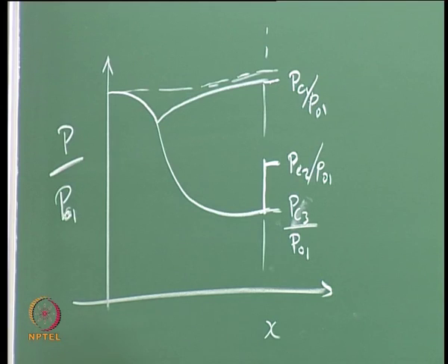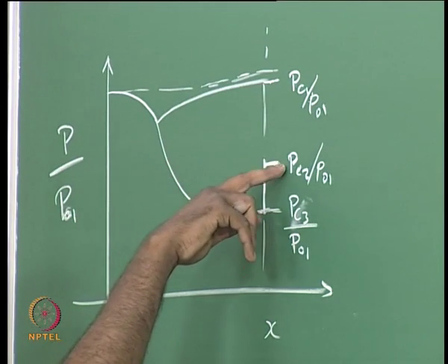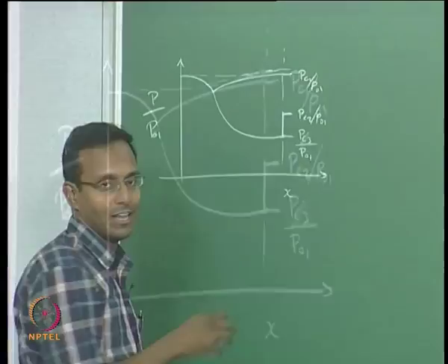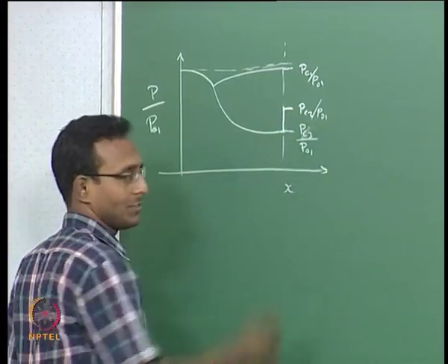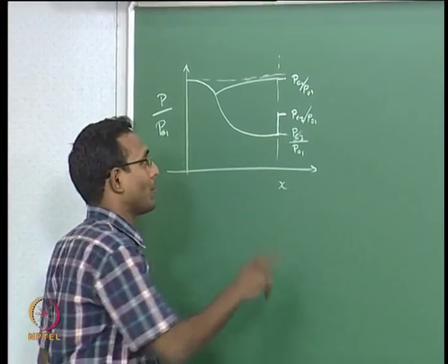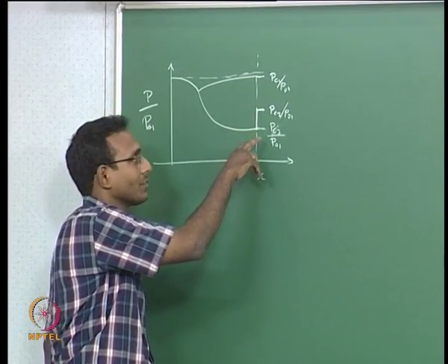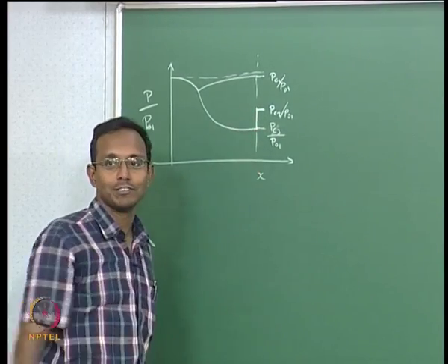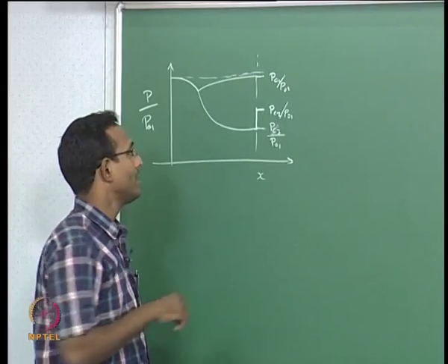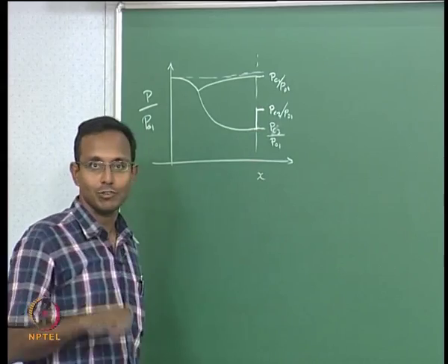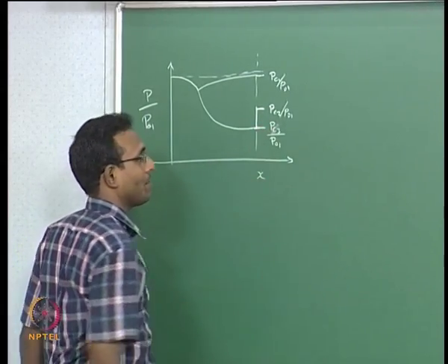Initially we said the flow changes inside the nozzle itself up to P critical 2. After that we solved, in the last class, the cases between these two, and of course we went up to a point where we said those oblique shocks that are forming at the exit finally become Mach waves, the weakest oblique shocks ever possible, and that just completes to become a Mach wave.